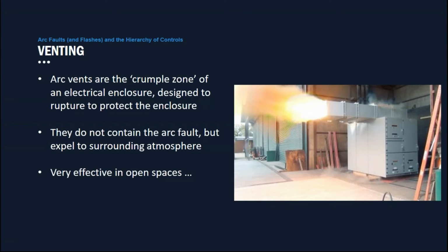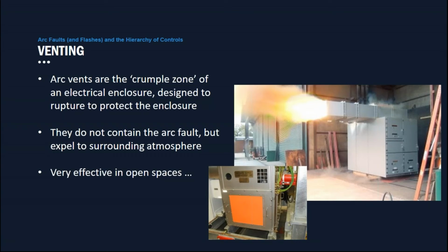And there's an image there of an arc chute where an arc fault inside is venting through that chute. Hopefully that's above head height. I don't have a scale on there. There's another image there of a simple panel, which is another type of arc vent you can have. In the case of the orange one, that is IP rated, so you can maintain your IP rating on the enclosure, but that vent is designed to open.